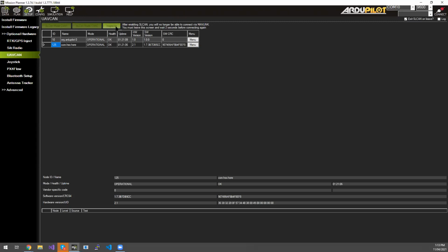So one of the biggest things: debugging CAN devices. Down the bottom here, you'd have the node status, the debug text that the node is actually spitting out. In this case, there is none. I've got the 1.7 firmware on this, so all of this debug text has been removed. If you have a 1.5 or 1.6, there'll be debug text probably every 5 seconds, telling you the load average and currently missed CAN frame output. But as of 1.7, this no longer exists.